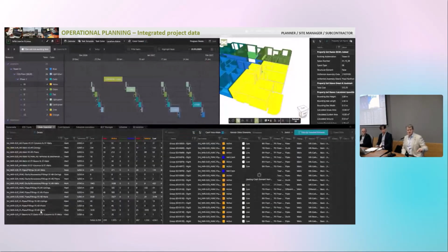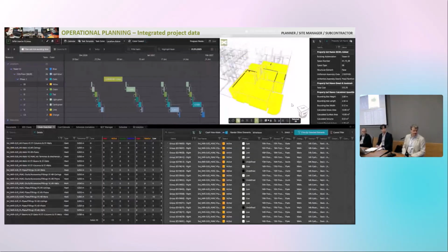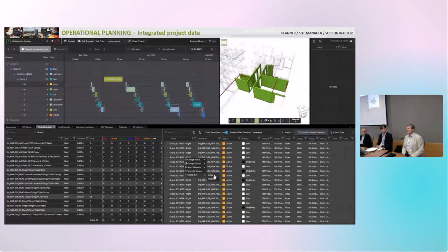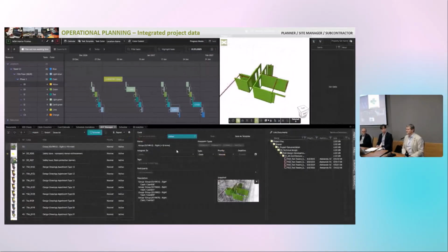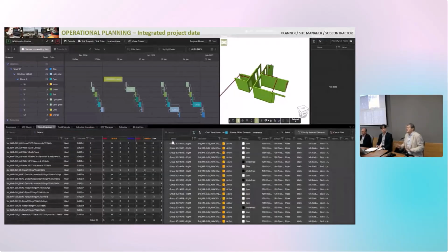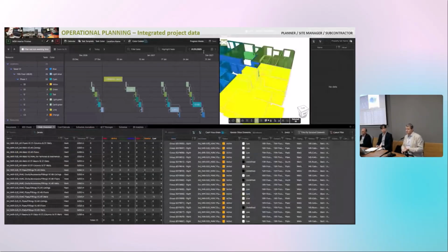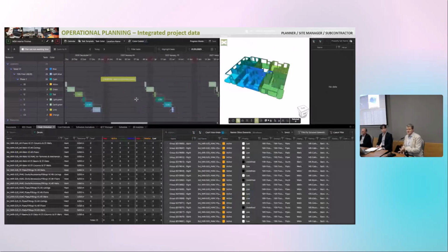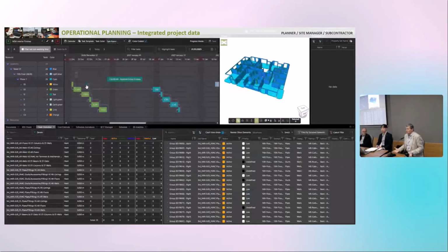And now the clashes. Now I want to see that there are, I don't know, I cannot read well, still 15 clashes in that apartment which are not solved. And I can create a BCF, send this to the subcontractor and say, now it's too late, but be aware, these are remaining clashes. I did everything I can. So I send you safety issues, the latest approved drawings, and all remaining clashes and quantities. So what do you want from me?